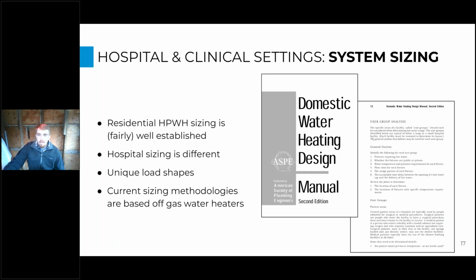And so I talked about first you need to size your system, and this can be a little bit tricky with hospitals and clinics. When it comes to heat pump water heater sizing, we're going to size a little bit differently than you would a gas system, right? Usually we're not just going to count all the fixtures and use the Hunter's curve to determine what our peak load that needs to be satisfied by the heater will be.